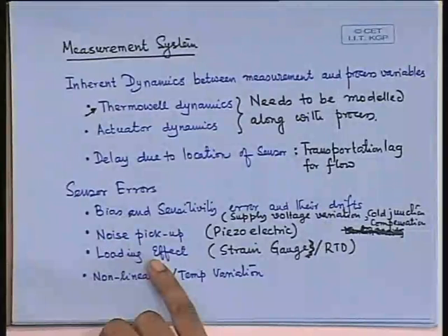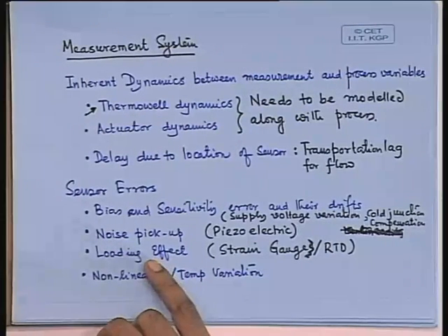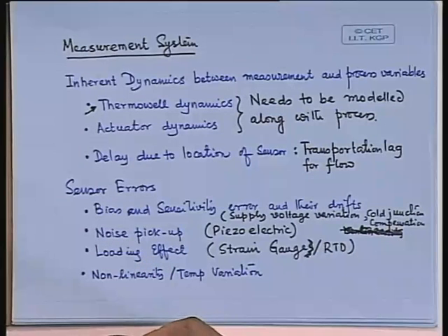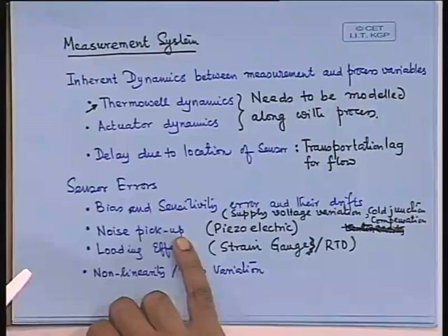Or heating furnaces, electrical furnaces. Electromagnetic interference is always caused by current, because flux cannot be created unless you have current. It cannot be created by voltage, right? Magnetic field is created by current. So any high current device you have is going to create electromagnetic interference. So you need to think of that.